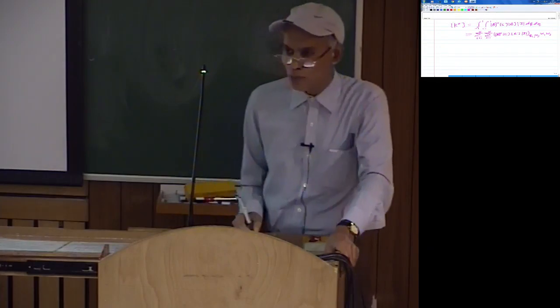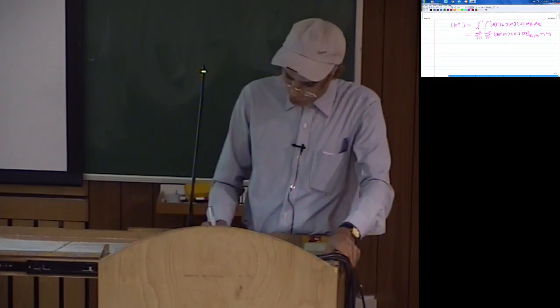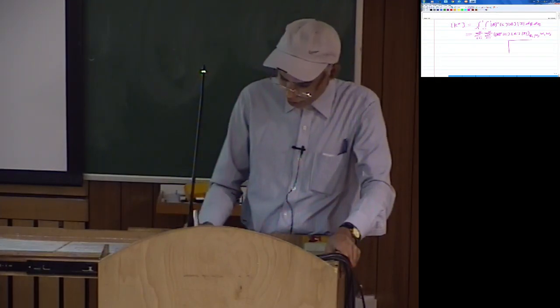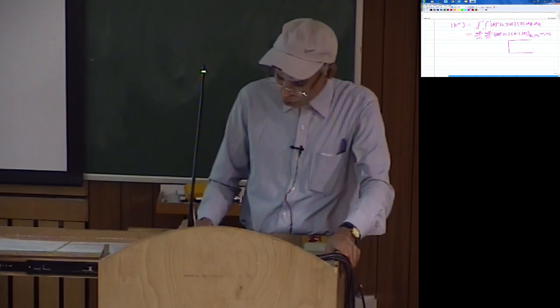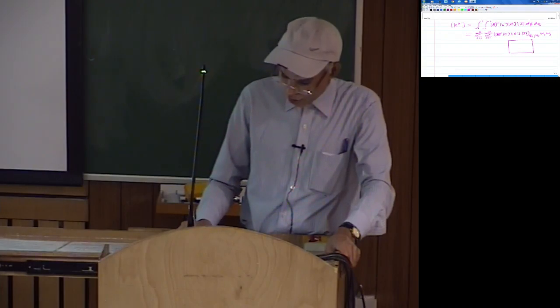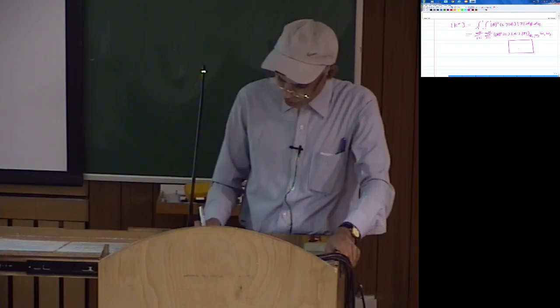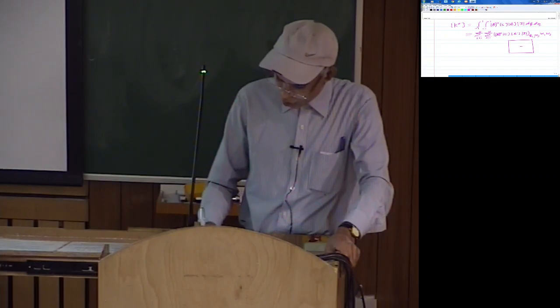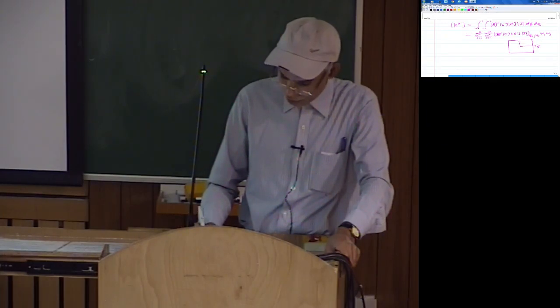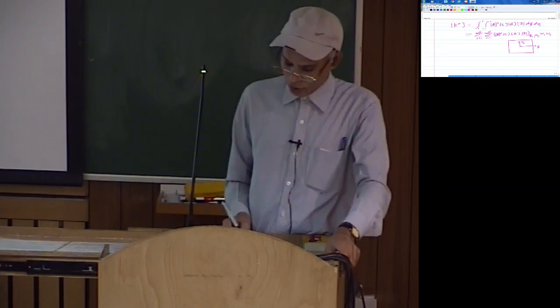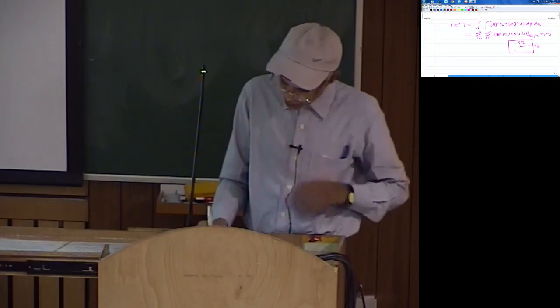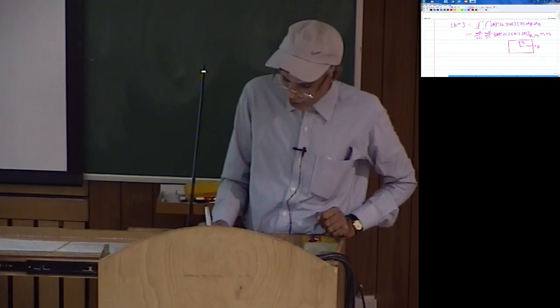What it actually means is that suppose you have the element, and let us say n is equal to 2, your element is a 4-noded element and the properties are such that two integration points are sufficient. Let us say this is xi and this is eta. Two Gauss points means 2 points in the xi direction and 2 points in the eta direction.